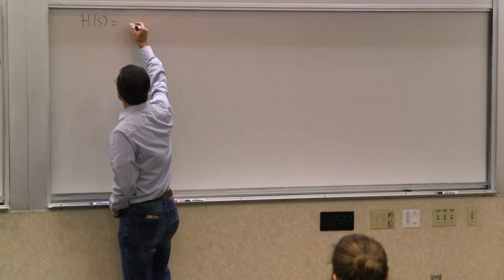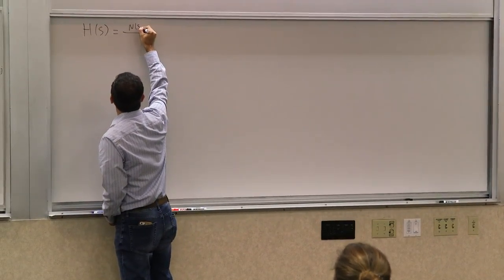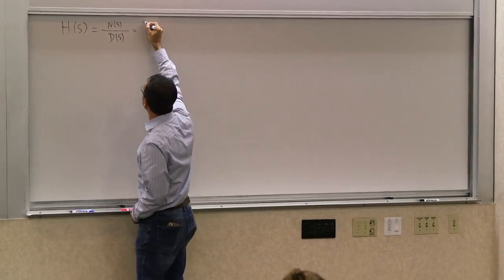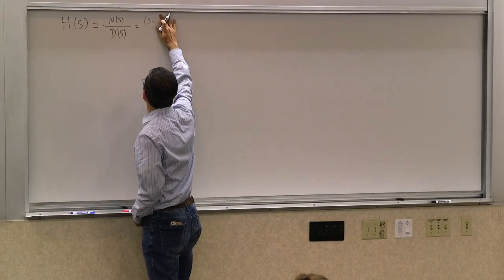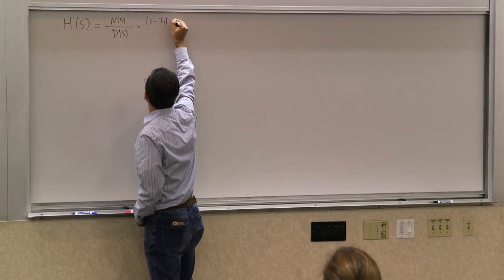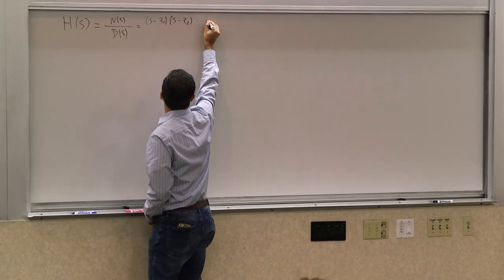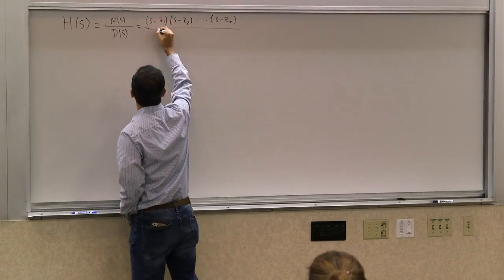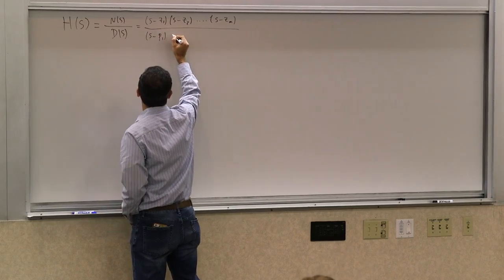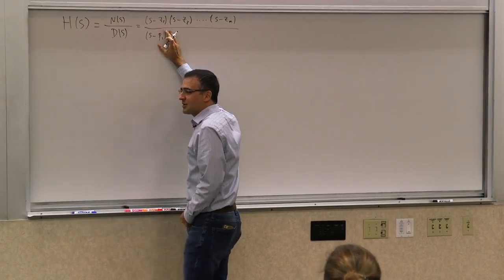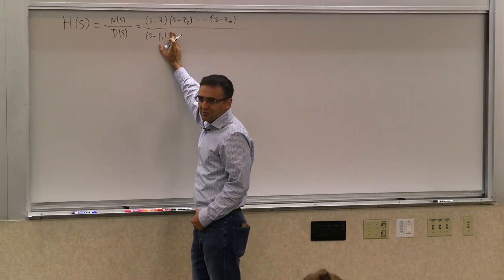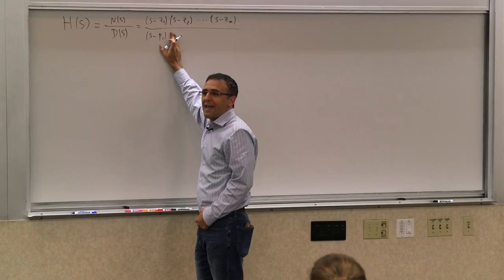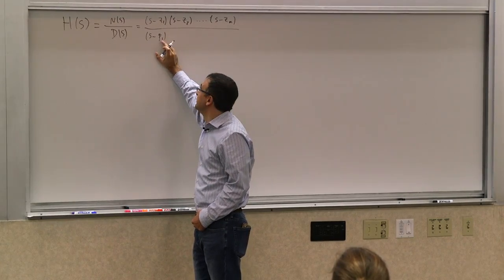So now, in general, if it's a rational function, you can write it as a numerator and a denominator, and each one of them has its own roots. So you can write them as s minus z1, s minus z2, and so on. These are the roots of the numerator, s minus zm over s minus p1. Now here's one thing that starts messing our notation. You remember p was the p operator, right? Everywhere you look, p is also used for poles.